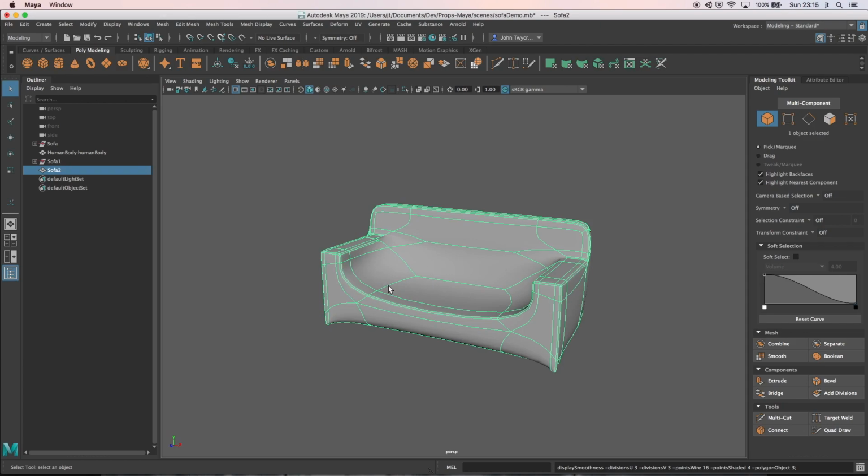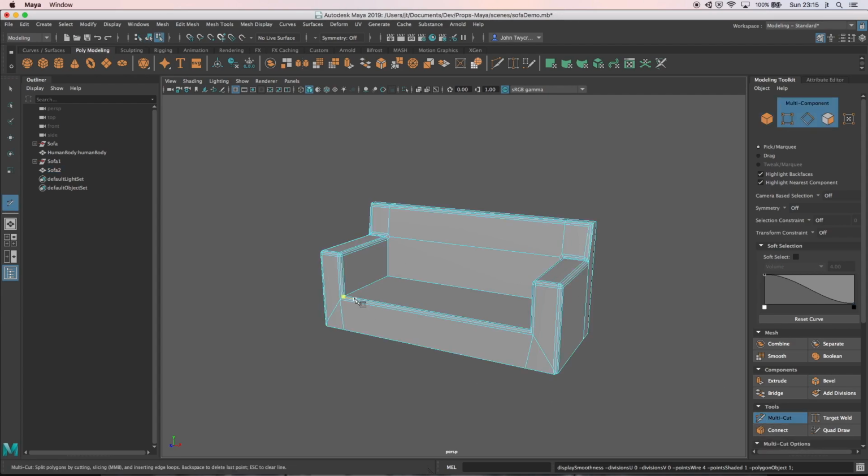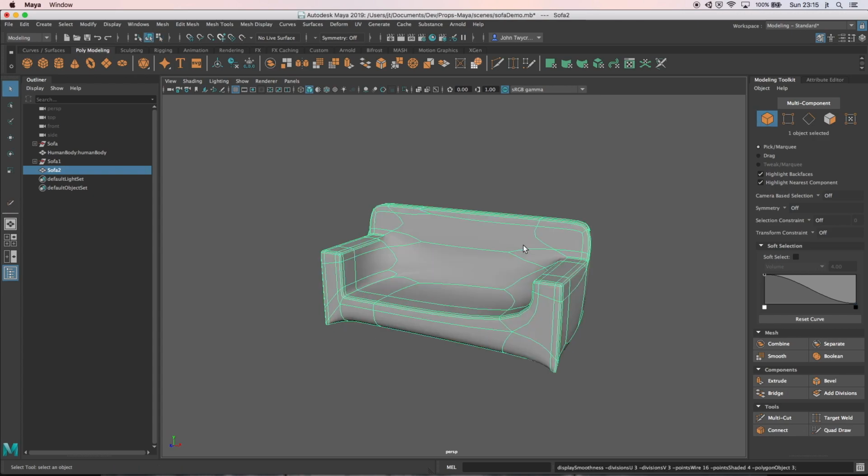Again, if I am smoothing it, where it's got these edges, it needs to have extra geometry in there. So I'll just show you. I am going to undo this because I'm not working to a smoothed workflow, but if I add in edge loops in certain places, then it will hold that geometry much better. So this bit was going very rounded. If I now look at this in object mode and then try and look at the smooth preview, I can see that it's holding it more.